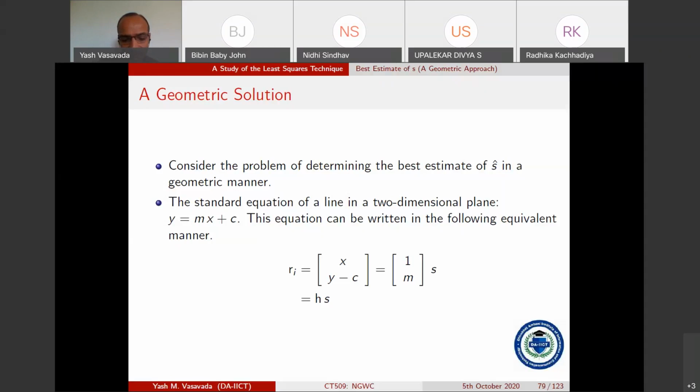But those measurements may not be directly one-to-one, because one measurement may be obtained when the surveyor was at the foothill of the mountain. The other measurement might have been obtained when the surveyor was maybe at a little bit of a height. Maybe there was a small hill or something like that. And so, yes, you have measurements of the height above the mean sea level of this entire locality, but those measurements cannot be put in one-to-one correspondence. Plus, individual measurements themselves may be having instrumental errors, measurement errors, and so on. So you do get multiple sets of measurements, but then how to combine them becomes the statement of the problem.